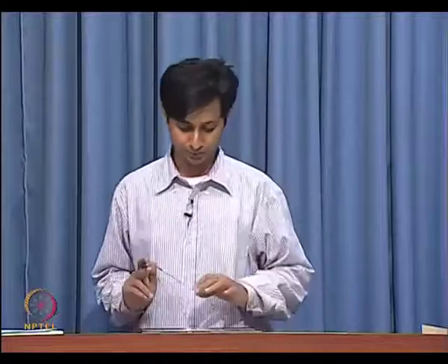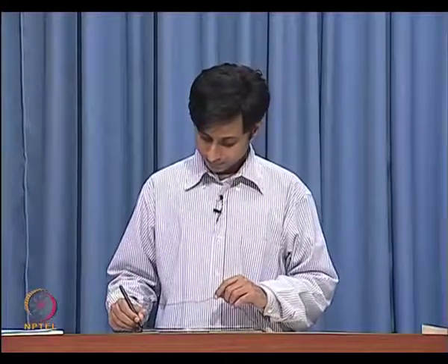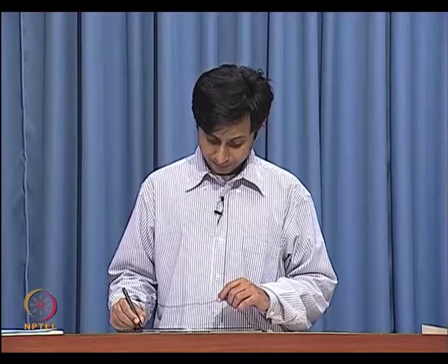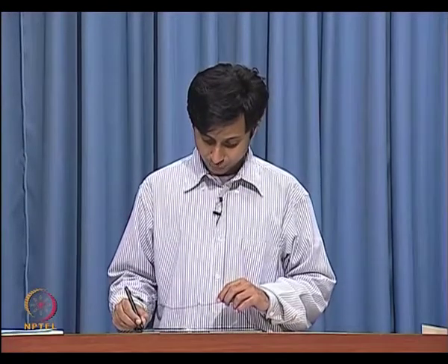Okay. We will look at oscillators and this phase noise business and where it is coming from, and we will take a look at all of this, but this is just a prelude to what is coming in future. So, we kind of understand the direct down conversion problem. LO can leak any time into the RF signal, and as soon as that happens, you get a DC offset, you also get phase noise problems.